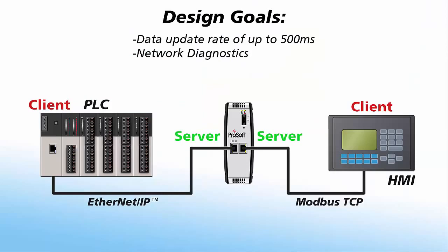This is acceptable for this application because HMI communications will not be outside our requirements of under 500 milliseconds. By using message instructions in the PLC, we also get diagnostics on the gateway's communication that can be monitored using your PLC programming software. Having access to this data can greatly reduce your time spent troubleshooting in the event of a communication problem.